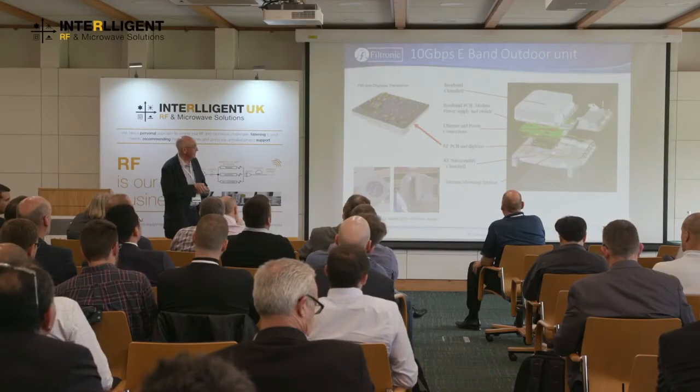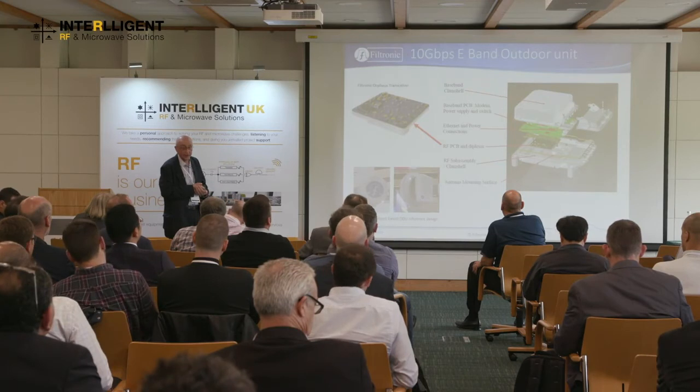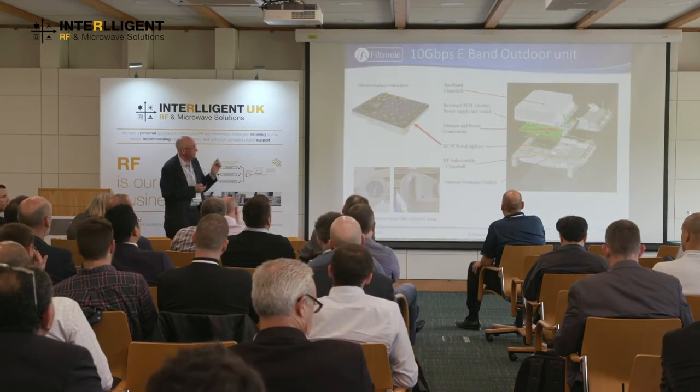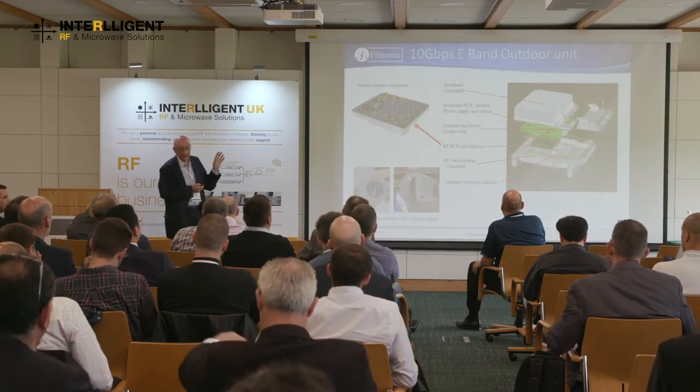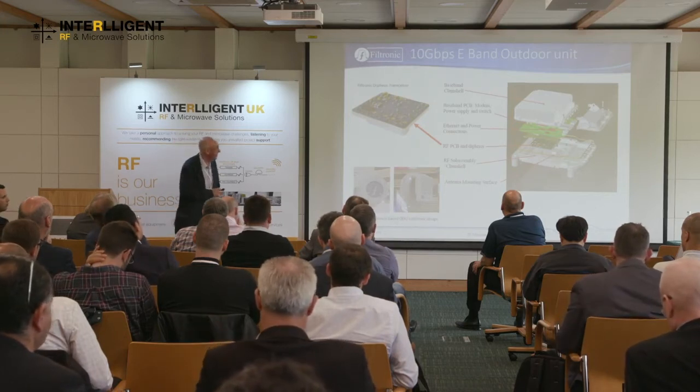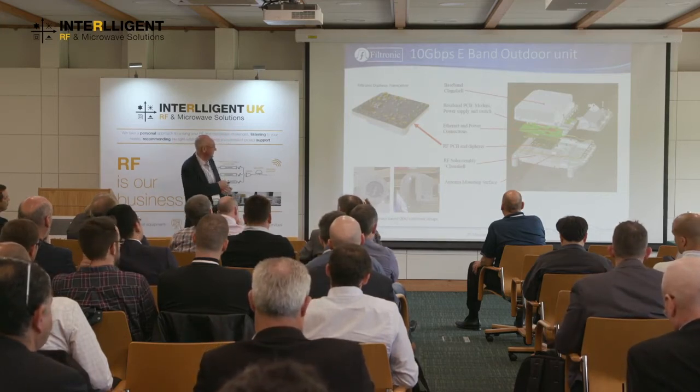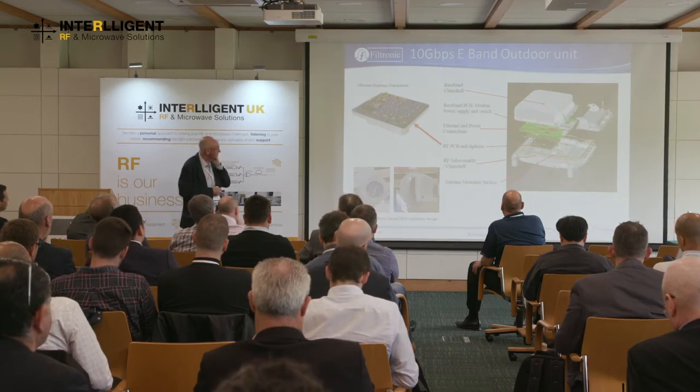The modem here is a very important part, obviously. And what goes on in the modem can compensate to a large extent for some of the impairments that we see, for problems like phase noise and phase matching on the baseband. A lot of error correction algorithms in there. So you can get a fair amount of system gain with a very clever modem design that compensates a lot for the shortcomings at the microwave frequencies.